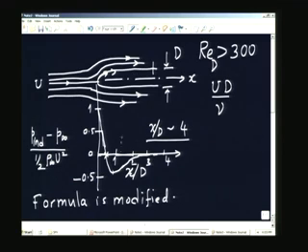Therefore, when I said the pressure has become equal to the static pressure, the meaning is very clear. From here to here, whatever pressure changes I am showing here are also the change of the pressure along the boundary itself. If you were to put a static hole all along this periphery and measure the pressure locally, you will see that there is going to be just this value. Whatever we are getting here is nothing but the static pressure variation along the boundary.